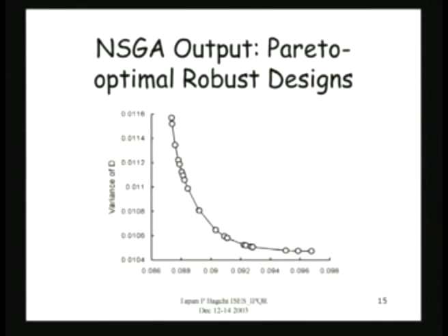These are the best designs as far as meeting the target is concerned. I'm able to meet first the target tau 1, and the second target, tau 2. Both I'm able to meet. One is with regard to cutoff frequency, the other is with regard to deflection. And the third thing it has done is minimize, to the extent possible, the variances. And these variances are caused by noise.